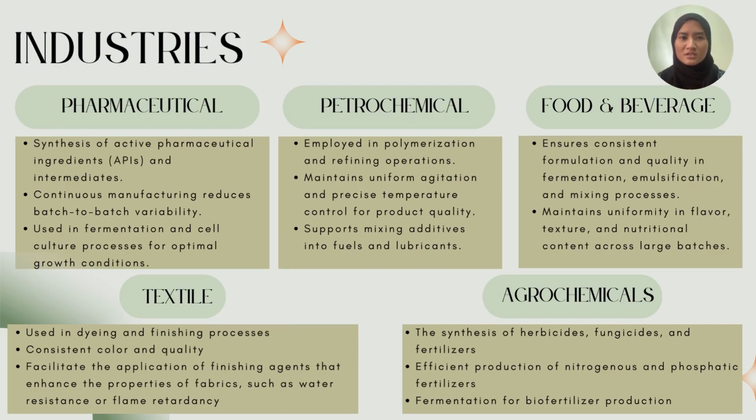In the petrochemical industry, CSTRs are employed in polymerization and refining operations. They maintain uniform agitation and precise temperature control, which is crucial for product quality. Additionally, they help mix additives into fuels and lubricants, enhancing their performance.